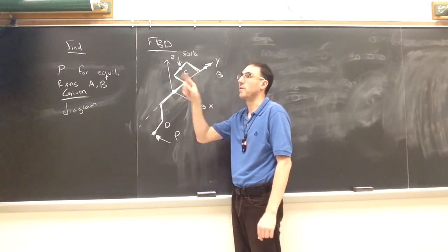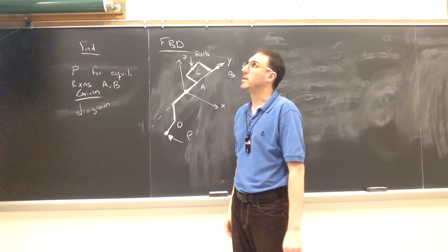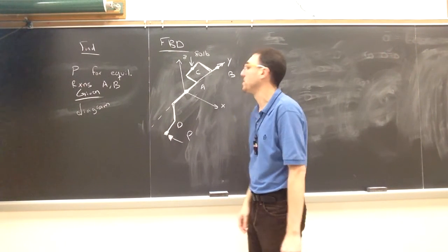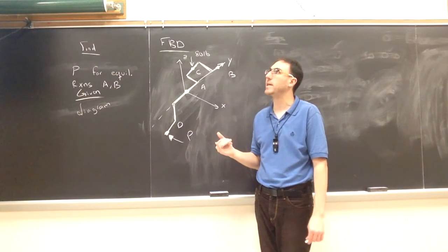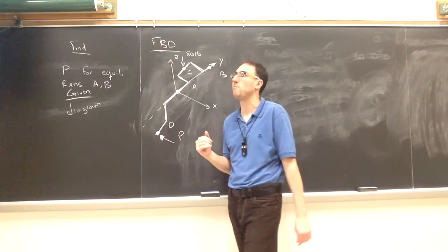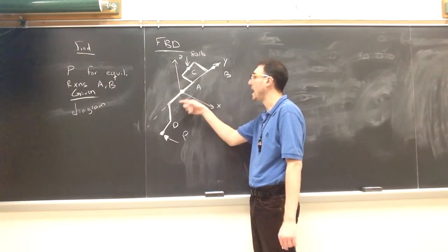They're each a bearing, but we have to look at how it's given to us. A is a journal bearing, and B is a thrust bearing. So we now know which type of bearing A and B is, and they tell us that the two bearings are properly aligned. We need all of that information to know how to model what's happening at A and what's happening at B.